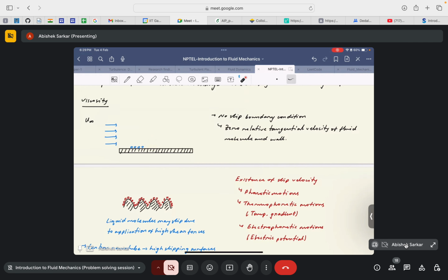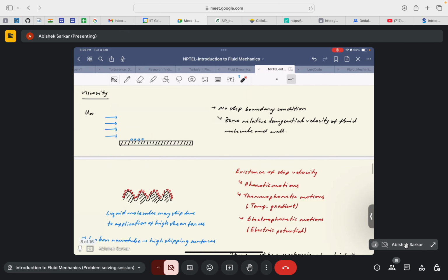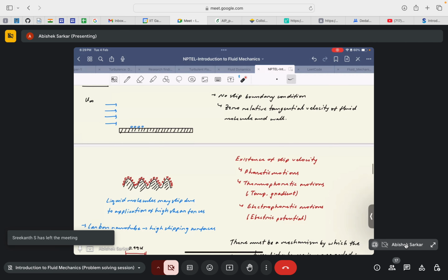That boundary condition is defined as a no penetration boundary condition. That we will eventually see if we encounter such kinds of problems. But these are two different boundary conditions. For relative velocity, we have the no slip boundary condition, and for the normal component of velocity, we have the no penetration boundary condition. So we need to distinguish these two conditions separately.